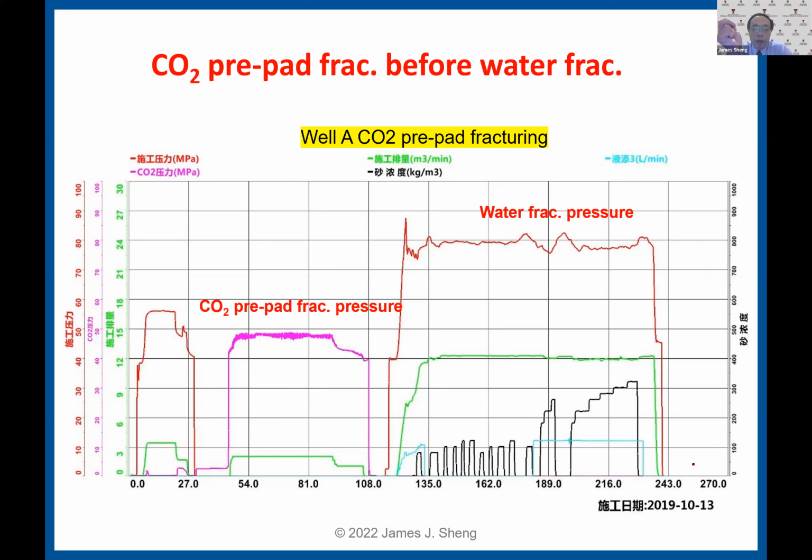So let's first look at CO2 pre-fracturing. Before they inject water to fracture the reservoir, they inject CO2 first. So CO2 contacts the rock first to get some rock dissolution, avoids water fracturing, and also provides high pressurized energy. That's the idea. This test was done in China.